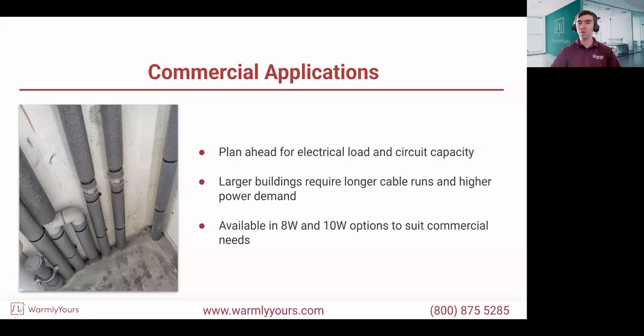Because of course, most of the time, to make the matter simple, if it's a 100-foot pipe, you very likely just need a 100-foot cable, unless of course there's some valves and stuff. But the wattage of the product is also extremely important, because just like Mary was saying, if it's a larger pipe and maybe there's minimal insulation, it is very likely you may need an 8 watt or 10 watt product, or a double run of the cable on each side, like the 7 o'clock and 5 o'clock position. So yeah, all of these pieces of information are critical.